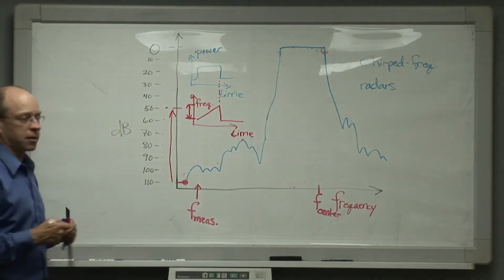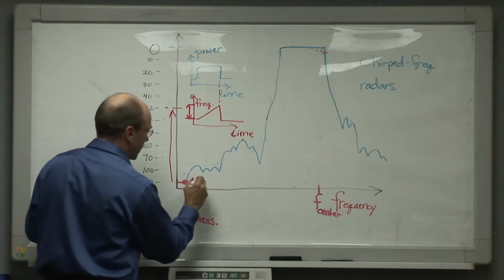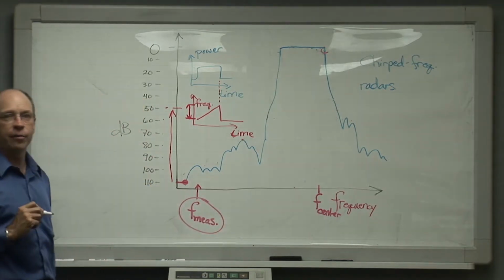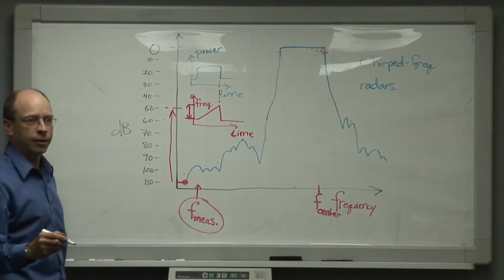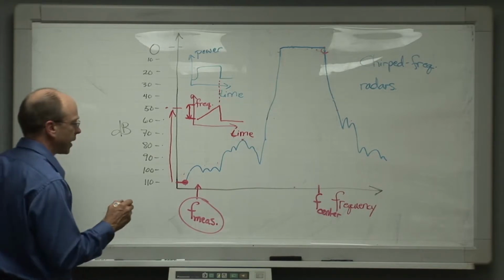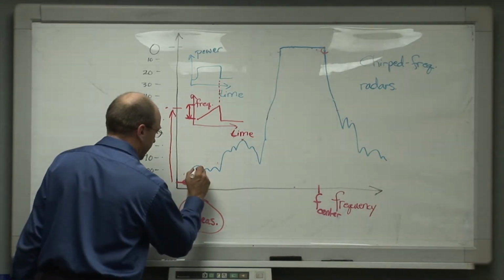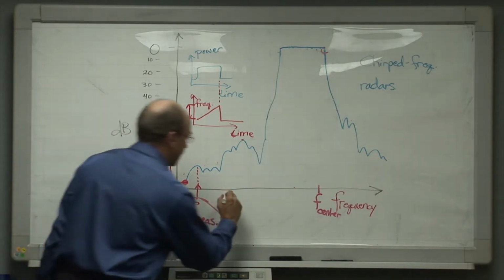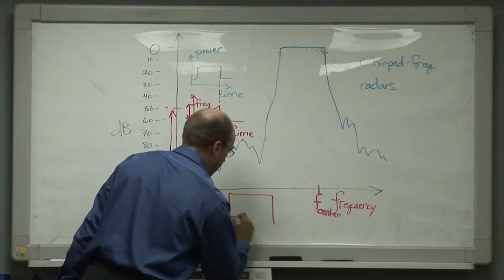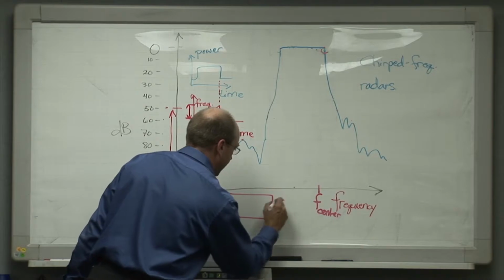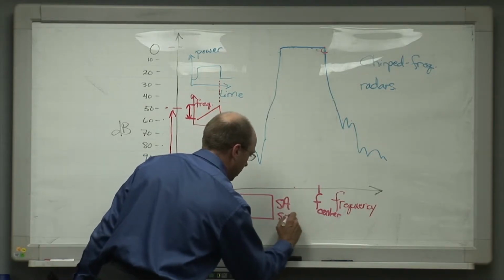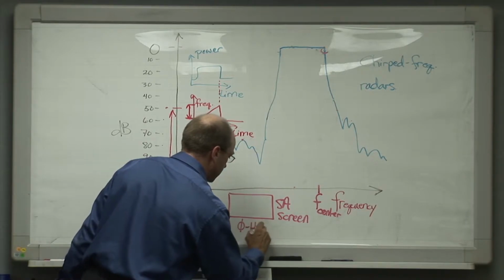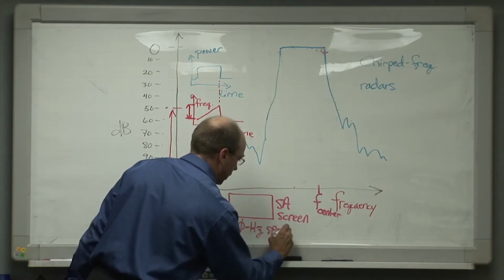We set up the measurement system, we set up the spectrum analyzer such that it is tuned to a single frequency on which we're going to do a measurement, fmes, and in the next talk after this one I'll discuss this algorithm in more detail. And when we tune it to this particular frequency, we set up the spectrum analyzer, this is the spectrum analyzer screen, in a 0 hertz span mode.